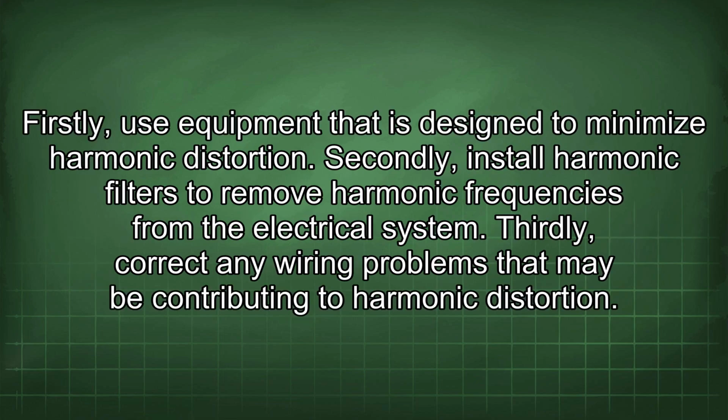Firstly, use equipment that is designed to minimize harmonic distortion. Secondly, install harmonic filters to remove harmonic frequencies from the electrical system. Thirdly, correct any wiring problems that may be contributing to harmonic distortion.